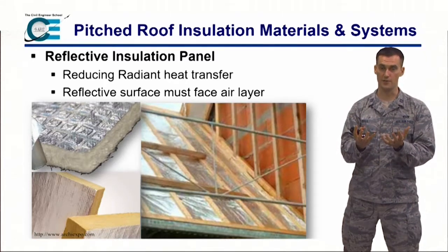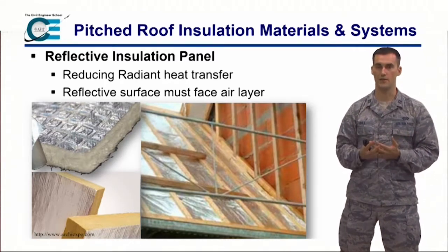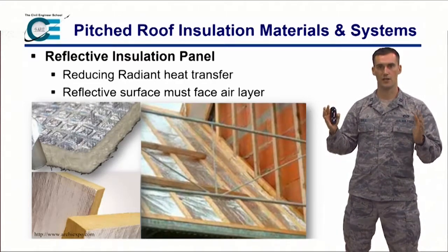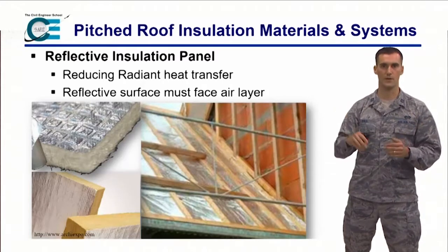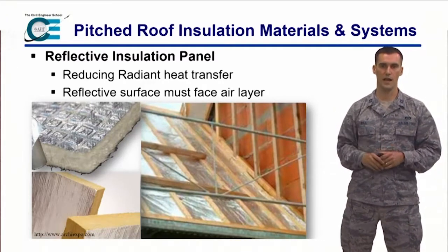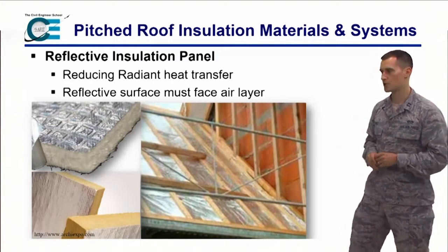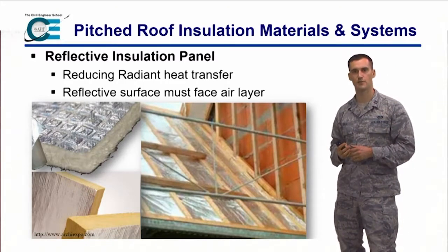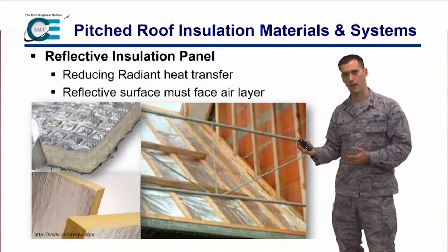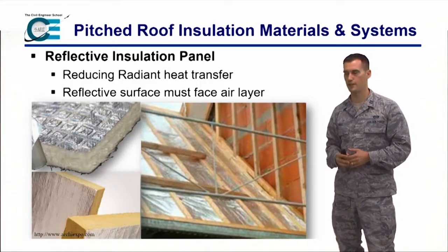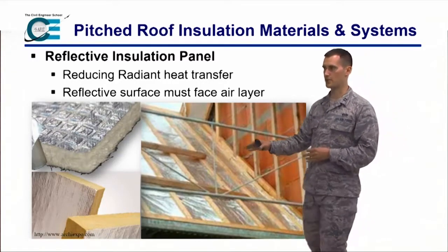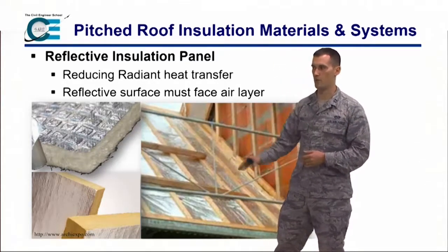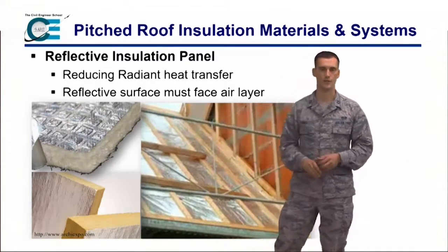If that were the case, you'd have what's called a convection oven. If you don't have a convection oven, you essentially just have two temperature differences and electromagnetic waves. Same way in a microwave. Okay? So one of the ways we could reduce radiation heat transfer, in an oven we want that, in our house we don't necessarily want that, is to install essentially aluminum foil, this reflective surface.